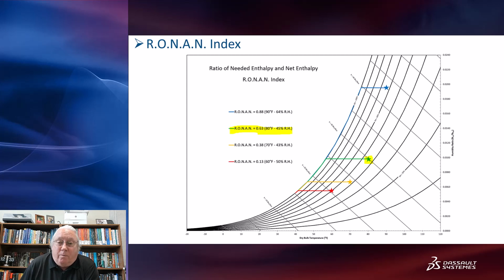So say we're starting from the conditions at this green star here. You start cooling down your condensation plates to try to get water to condense out of the air. You're having to put in energy, and you're having to extract heat from those condensation plates. And when you're doing that, you're moving horizontally here. We're just changing the temperature, and we're getting closer and closer to 100% humidity. So you go straight across here as you're cooling your condensation plates. And as you go across there, you're spending energy, but you're getting no water.